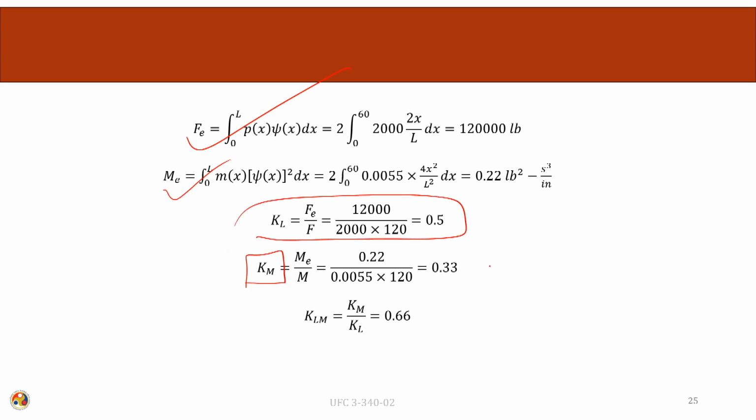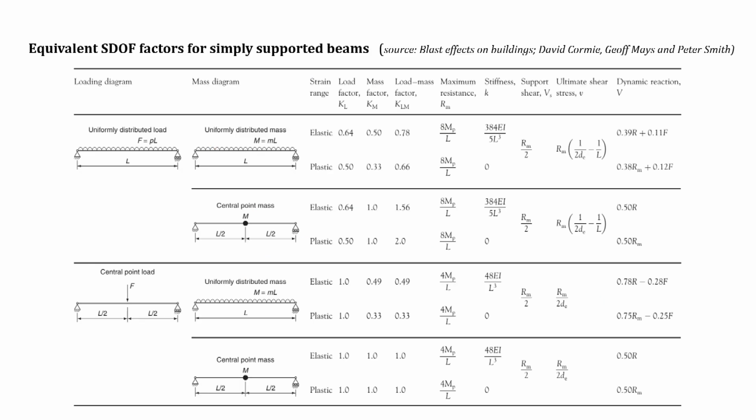Earlier my equivalent mass was 0.5 in an elastic curve, now it is 0.33 for a plastic curve. This way, using the load factors and the mass factors, we can cross verify our calculations. These curves we can use to calculate our equivalent stiffness, our equivalent mass, the load factor, mass factors and the load mass factors.